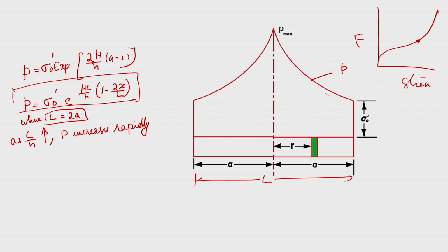That means whatever force you are applying will be completely used inside the die cavity, and the pressure or stresses inside will be very high. So complete filling of the die cavity takes place, and when the pressure still increases, the metal will skirt out through the flash and fall into the flash gutter.